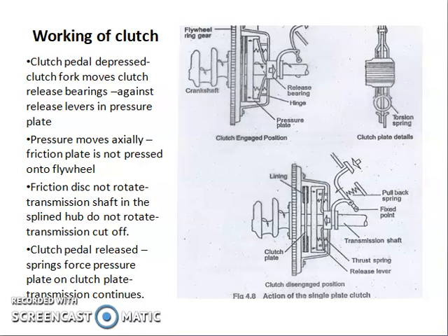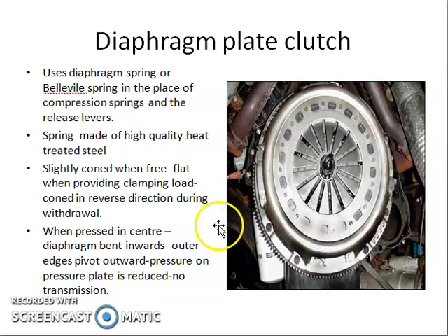You can always see many varieties of other clutches where modifications are being made in the springs that are being used. One such modification of clutch is called a diaphragm plate clutch. This also has all the parts. You have the flywheel and the friction plate which is attached to the flywheel, and over that you have the pressure plate. But instead of the compression springs, we have the diaphragm springs or the Belleville springs.